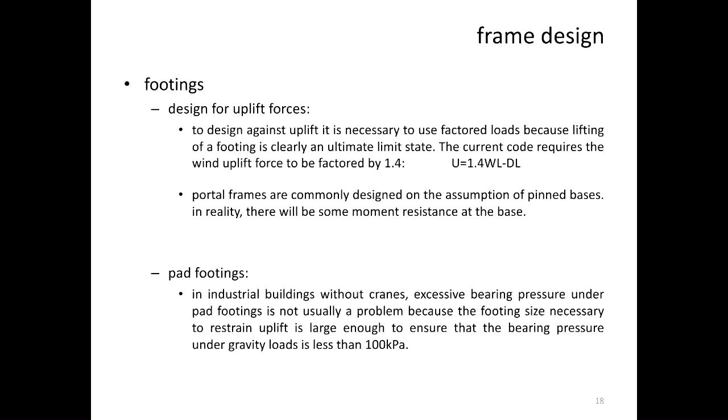So those footings which are under the ground also provide some uplift resistance as well, if that makes sense. Okay? So that is why we have to make sure that our footings work under not just gravity load, but also against uplift.